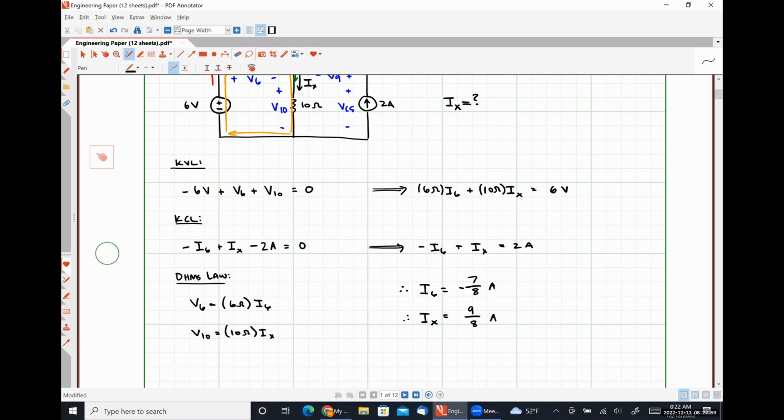So why are the 9 ohm resistor and the 10 ohm resistor not in parallel? Because they share that top middle node, but the bottom node isn't the top right node because there's a current source between them. So if we identified our nodes with colors, they wouldn't be between the same color, right? That top right node and the bottom node are not the same.